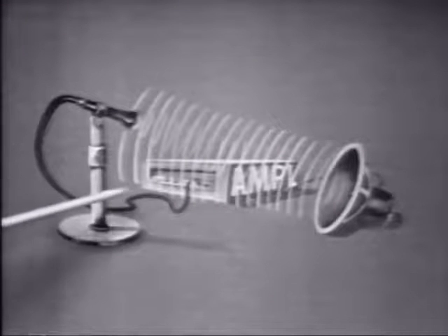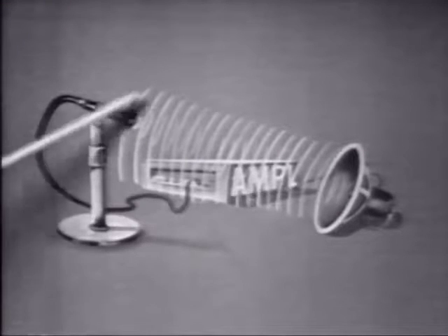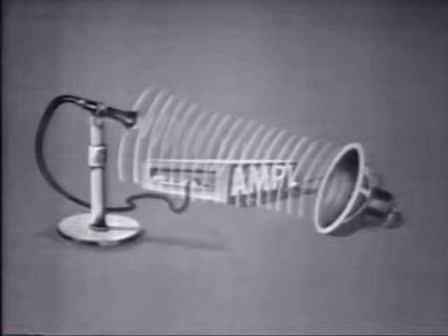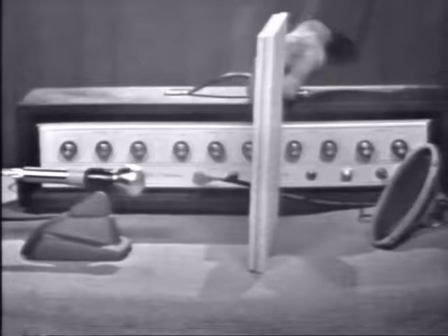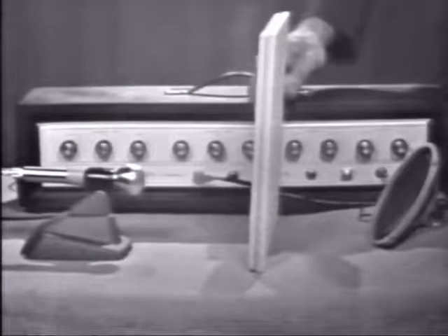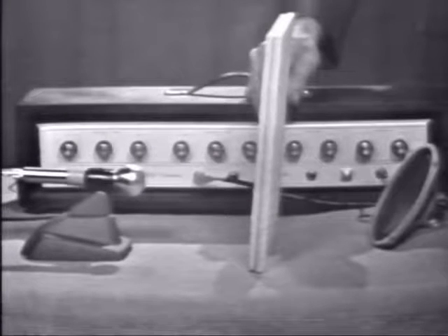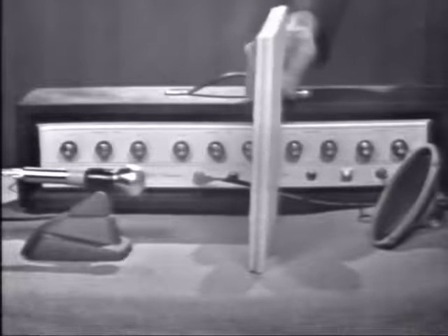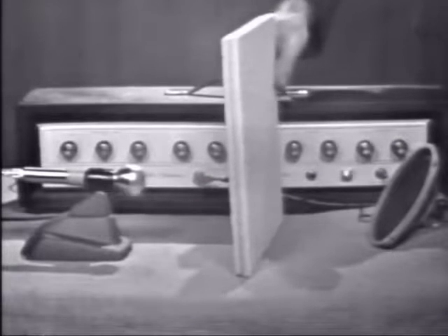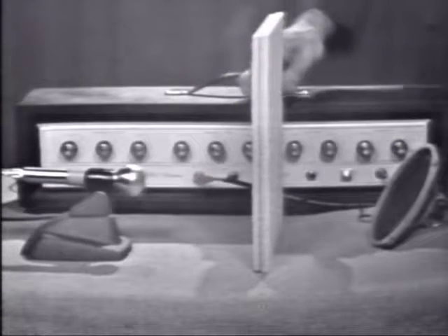If the microphone picks up the sound coming out of the speaker, the output is feeding the input and the stage oscillates. Now, since there's no way to control the amount of feedback, the strength of the oscillator signal continues to increase. You can hear this increase when we remove the tiles slowly and allow the microphone to pick up the speaker's output. The squeal builds from a relatively low level to a very high level.